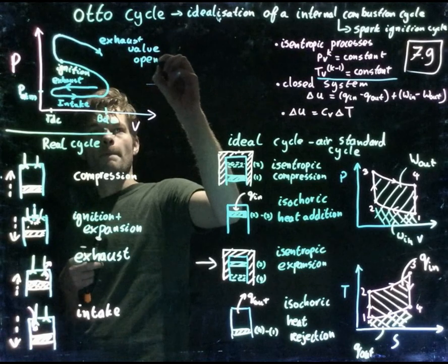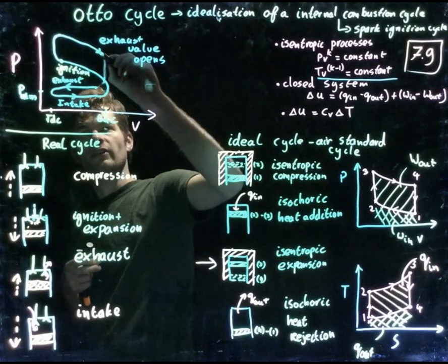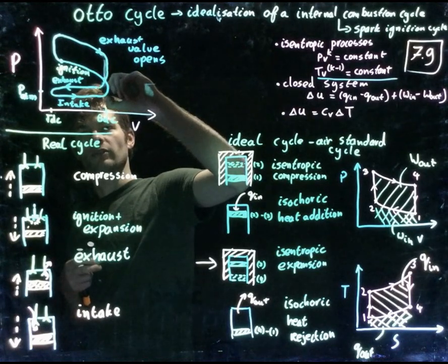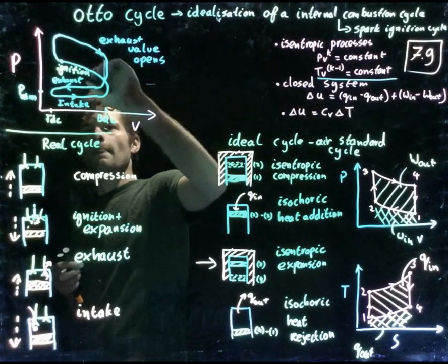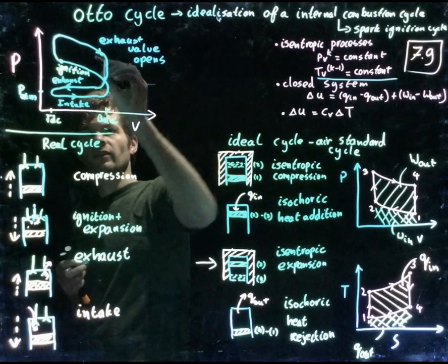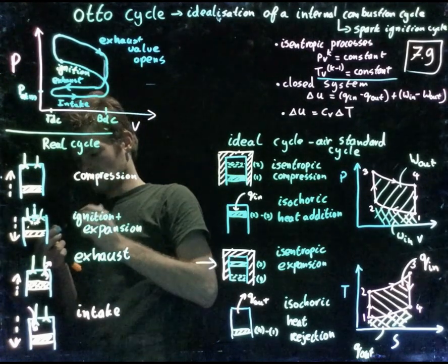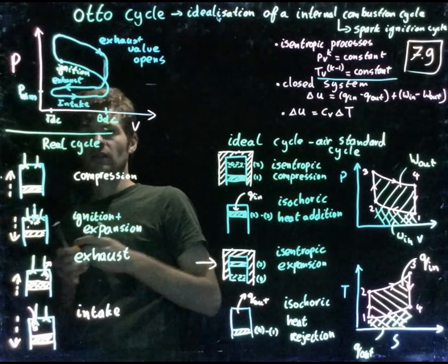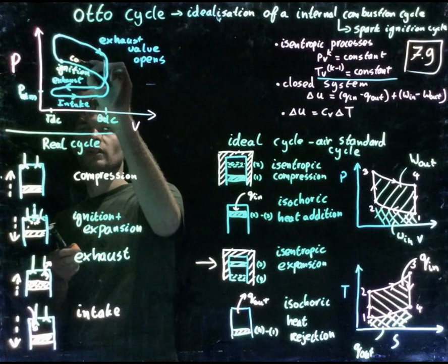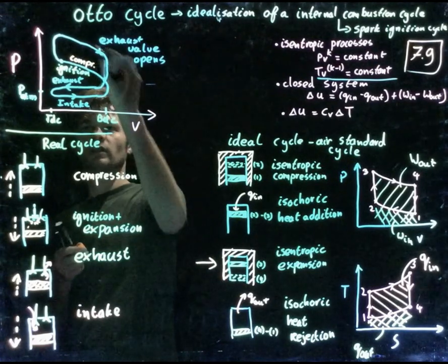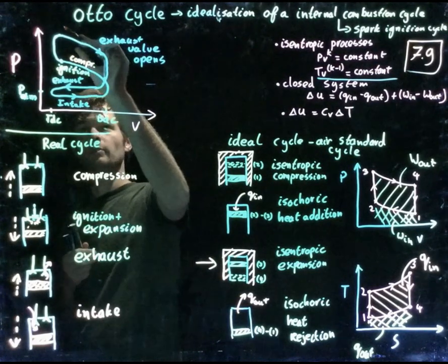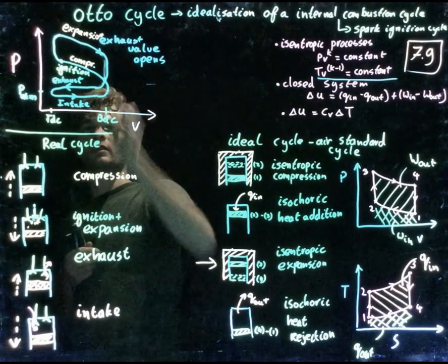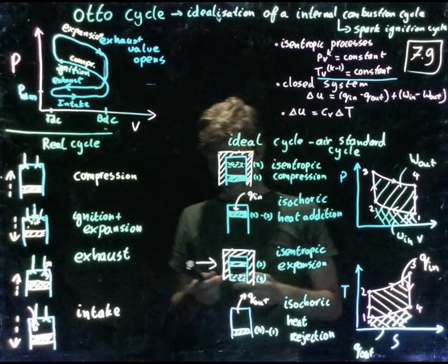So from there, fumes are going to be removed and pressure is going to decrease. So over here we have ignition. This is the compression stroke. Just use another color. Here we have compression, and here we have expansion. So this is what it looks like in reality.